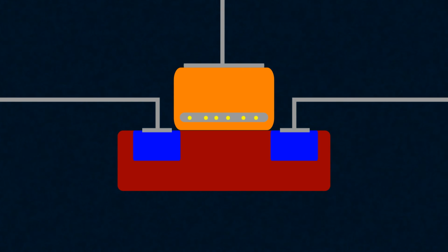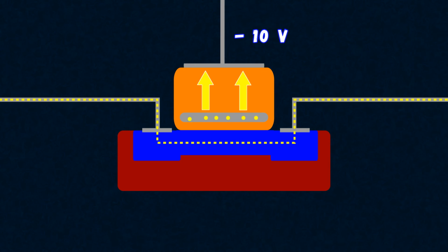All right, we've filled the floating gate with electrons, rewriting the stored 1 to 0. How do we now perform the reverse operation and remove electrons from the gate, turning 0 into 1? Well, essentially the same way, only now we need to apply voltage in the opposite direction so that it pushes electrons out of the floating gate. Of course, thanks to the same tunnel effect.